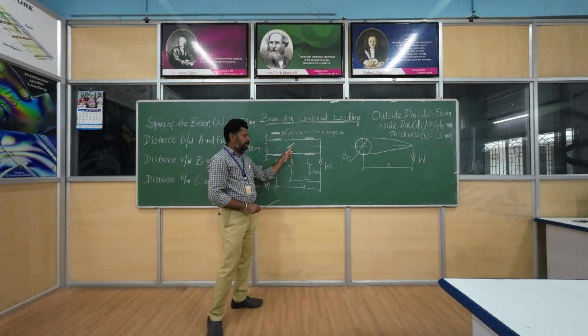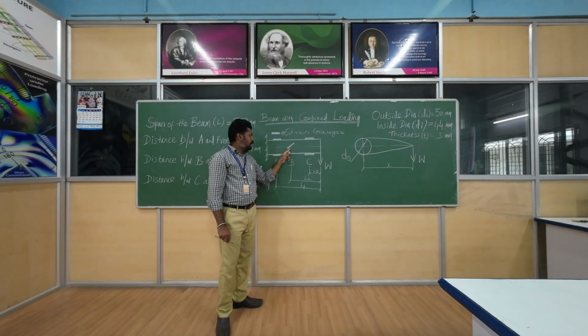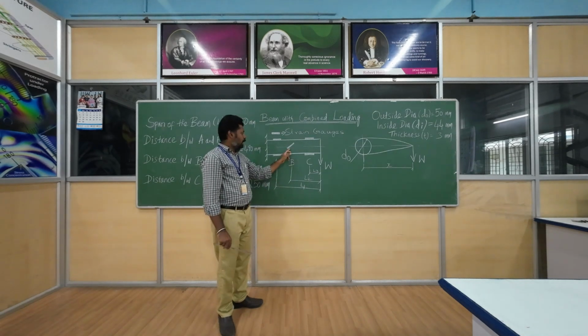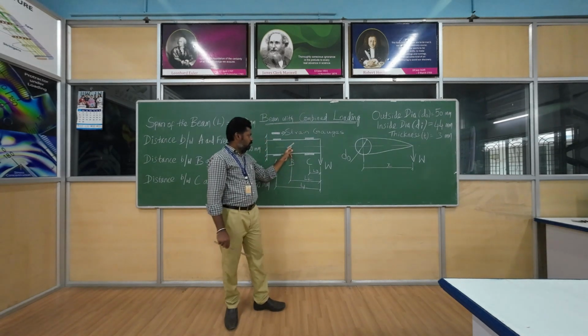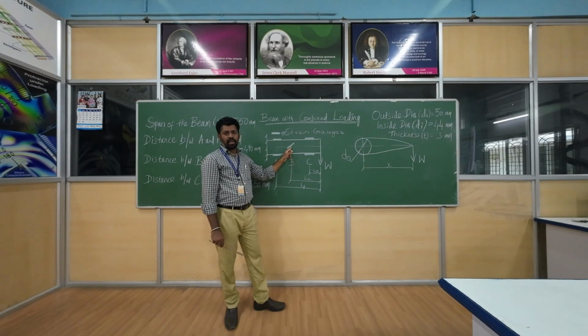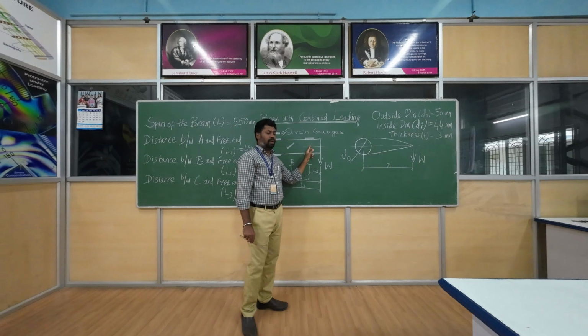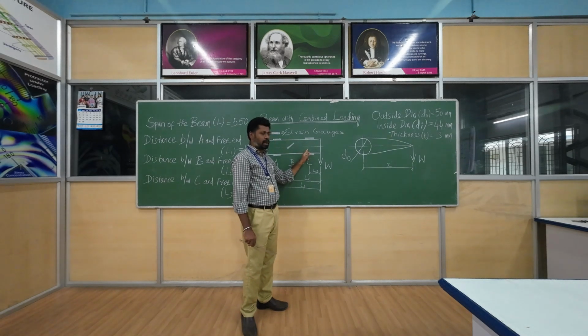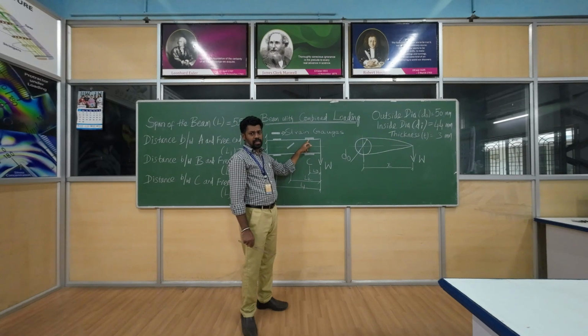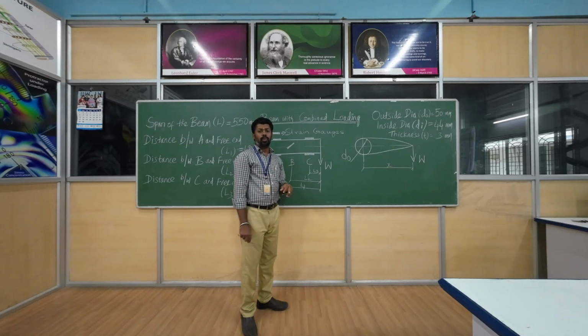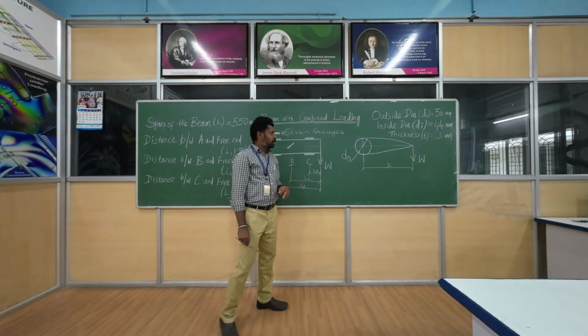Again at section B, the strain gauge has been mounted at 45 degree. The purpose of mounting at 45 degree is to get the shear strain. Again, for section B, we use single strain gauge that leads to quarter bridge circuit. Again coming to C, to compute the normal strain due to bending, we use two strain gauges at top and bottom of section C. Again this leads to half bridge circuit.